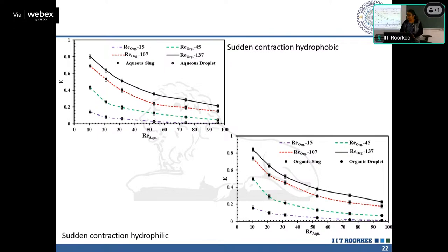So that is what I am telling: it is not only one factor that is giving you the idea. Any transfer rate, whether it is reaction or mass transfer, is governed by two logics. One is the specific area of contact. Second is the residence time. If you recall, in such cases the transport process is governed by molecular diffusion, which is a slow process.